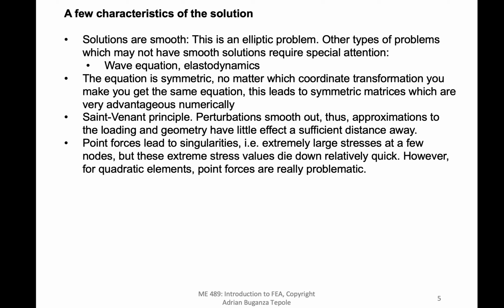In some cases, you should not be applying point forces because they lead to singularities, very high stresses that are not realistic. So in many cases, especially for example for quadratic elements, you might want to reconsider and try to apply actual tractions, force per unit area, instead of point forces.